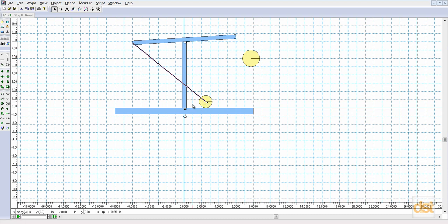The other thing we need to do is make sure that this body right here rests on the surface of this plate. By default, bodies are set to collide in Interactive Physics. Sometimes that's what we want, other times that is not what we want. For example, if this beam spins around, one side of the beam is going to collide with this post right here.